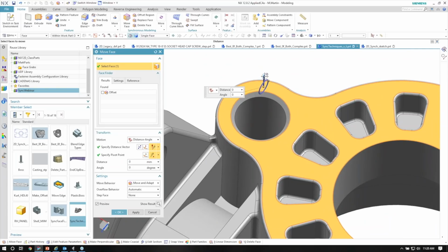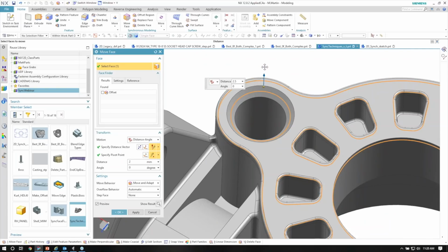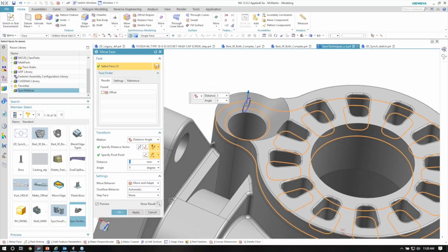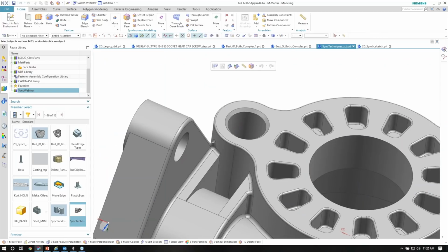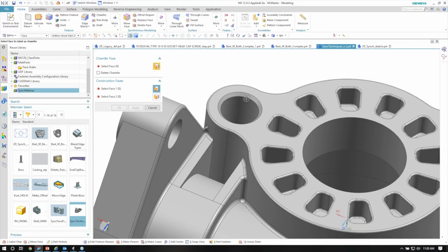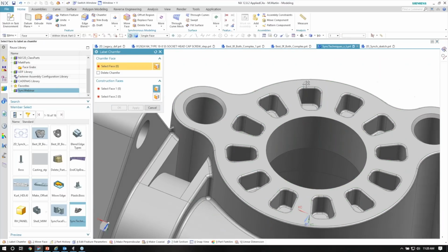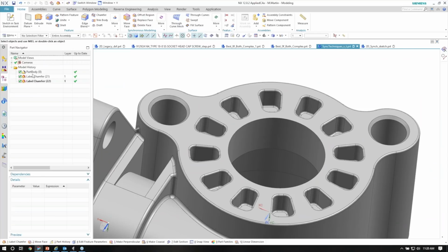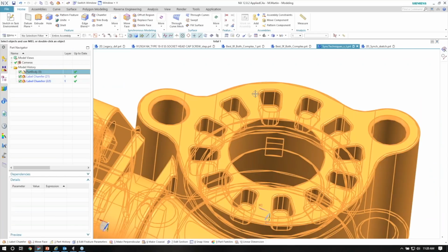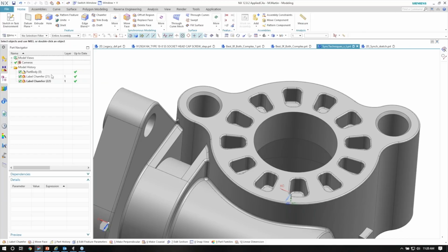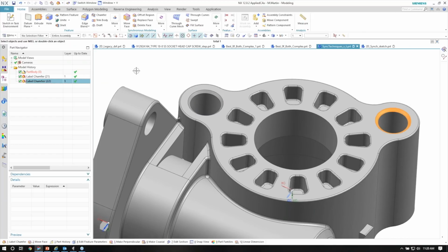As I start to drag this up a little bit, you'll see that my chamfer is not staying as a chamfer. It's just blowing out the rest of my hole. So I'm going to cancel this. Now on my synchronous toolbar, there is a label chamfer right in detail features. So I'm going to pick this chamfer, apply that, say okay there, and now on my tree I've got a part body, which is just a parasolid that is where I open this from, and it's got a couple label chamfers in here now.